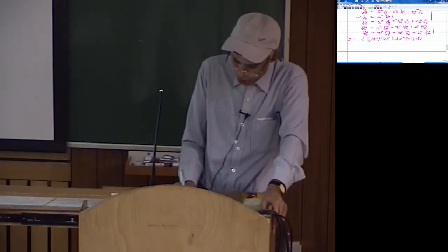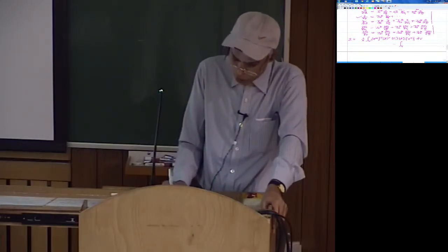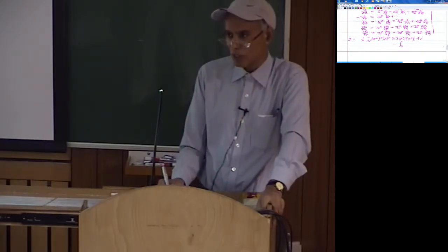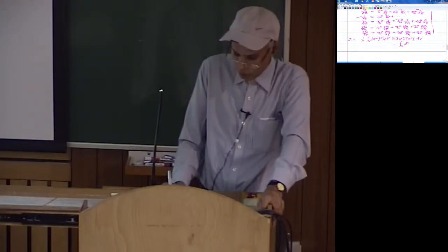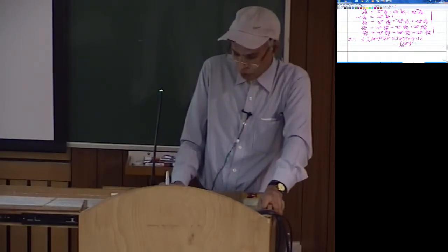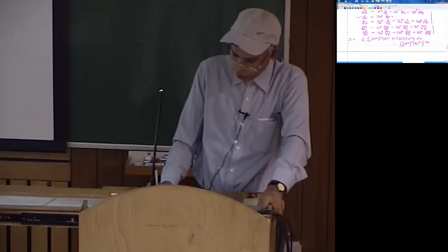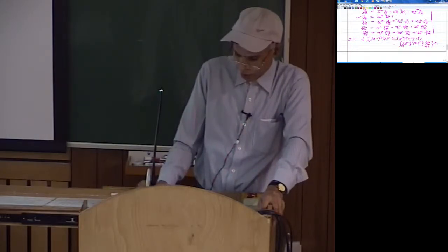And of course the other terms are then the body force term, which is integration again over volume, u, v, w transpose into fBx, fBy, fBz, and that is H into dE, so it becomes dE transpose into H transpose, and then of course you have the body force vector fBx, fBy and fBz dV.